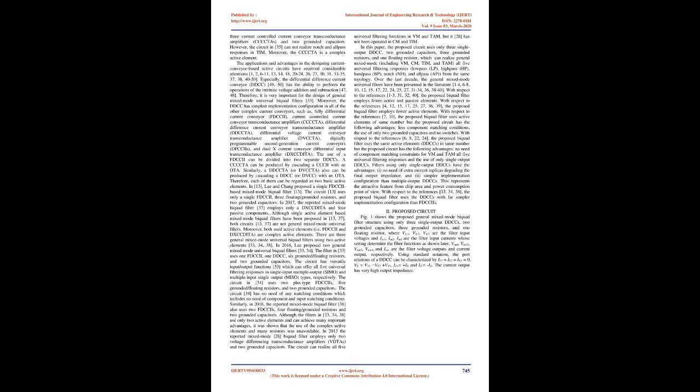In 2018, Zanjani et al. proposed a mixed-mode GMC biquad filter [39] with independently electronic tunability. However, the filter needs to employ 19 inverters as operational transconductance amplifiers and 2 grounded capacitors.